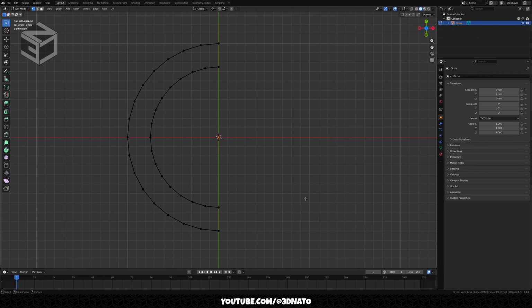Let's create the device. Select this top vertex, press Shift+D to duplicate it, Y to lock the axis, type -20 and hit Enter to confirm. This duplicates and moves the vertex -20 millimeters on the Y-axis, without creating an edge between them. Select this bottom vertex, press Shift+D to duplicate it, Y to lock the axis, type 20 and hit Enter.